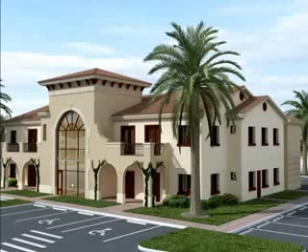In both cases, I didn't want the viewer to be able to see inside the building clearly enough to see that there's not much in there, and I also didn't want the viewer to be able to see what was being reflected because it was a generic building and I didn't want to give any indication of what was actually going to be reflected in real life. I just needed something to be reflected rather than just a simple horizon line, which is never a good thing in visualizations. So these blurry reflections are a great quality to add to your scene if you need them.